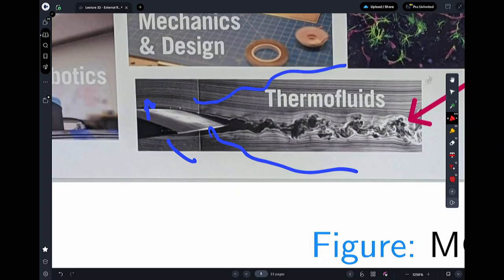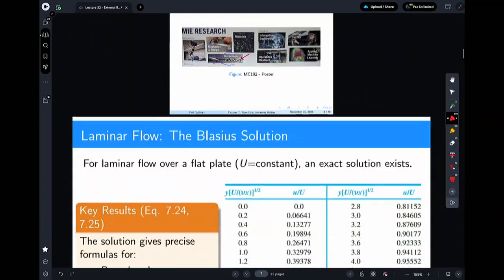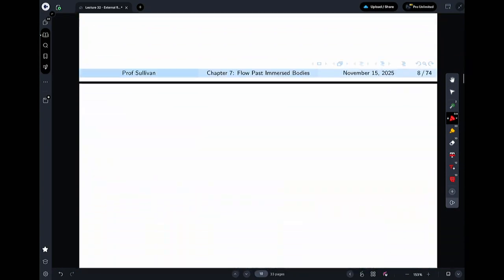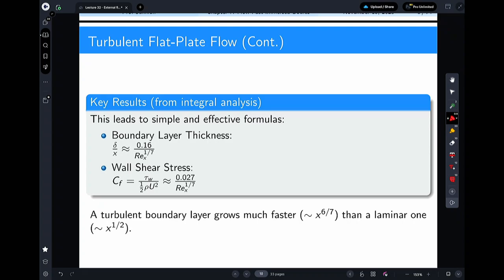You see this black region that is before the trailing edge of this wing? That black region is the viscous layer. So that's where viscosity is playing a role. Everything outside of that is the external flow. So the flow is affected right near the wall. Okay? In all of these cases, you can't have a zero flow, because if you had a zero flow, there'd be no flow, and Reynolds number would be 0.